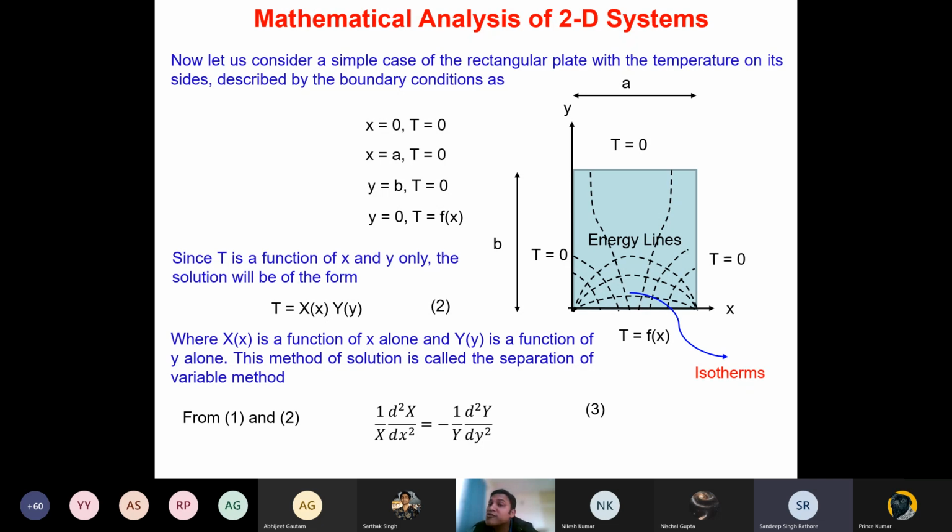Because the Fourier series gives you a combination of sine and cosine waves, and a combination of those can represent any function, be it linear, be it cosine or sine, be it exponential. Any type of curved line can be represented by a Fourier series. And that is the reason why the Fourier series or Fourier transform is used in signal processing.